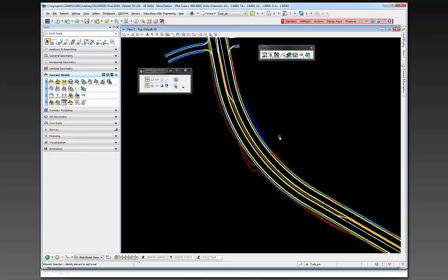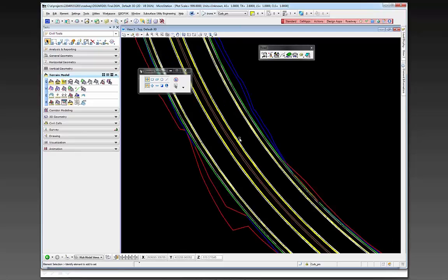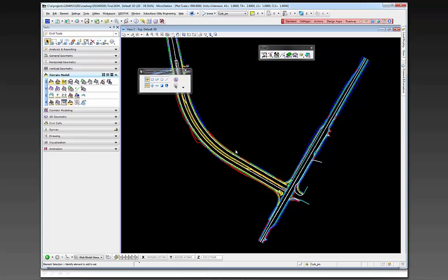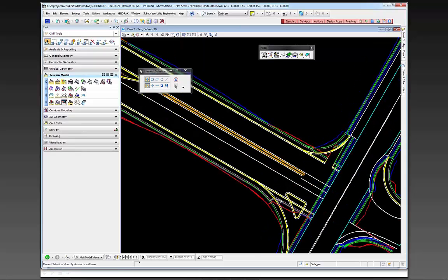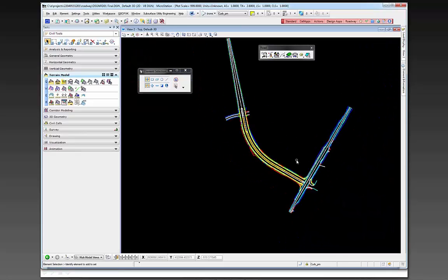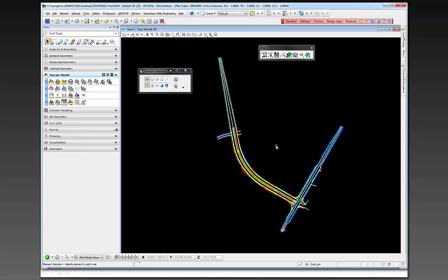And if you remember back on that image, the very first image of the slide, you could see that view, and that view is what they're really looking at. They're going to create the proposed surface from these lines. It looks like I have some extra lines in here that I'm not really going to worry about at this point. You can see where some of these break lines are crossing down here at the intersection. This would all need to be cleaned out. But all I'm really trying to do is show you the workflow to create the file to put in the deliverables folder.